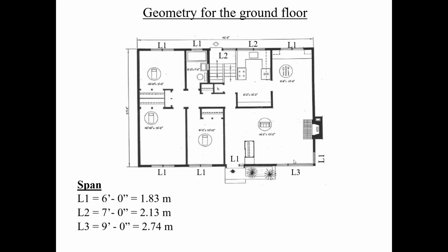Of course, since this is longer. But all these other ones here, even though it's not exactly 6 feet, it would maybe be 5 feet. You don't care. You would design this lintel here, and you would put the same lintel here. Even for this window here, it's slightly smaller. So whatever I design here, I'm going to put it there. And of course, this becomes the...